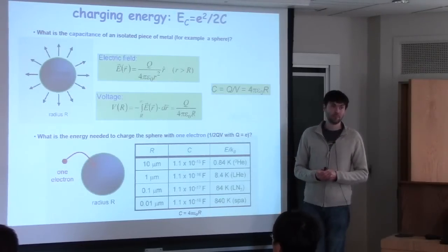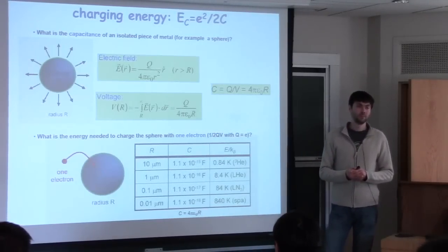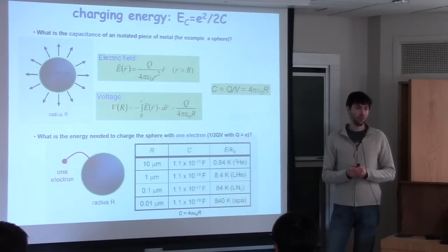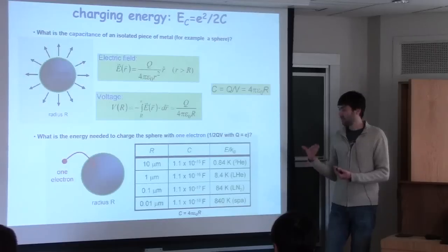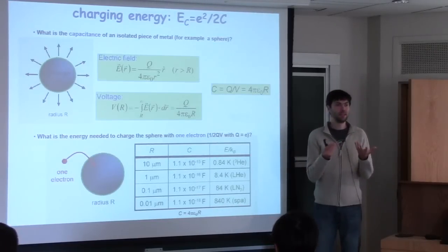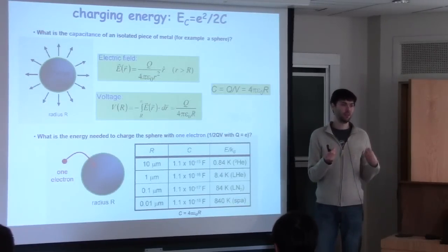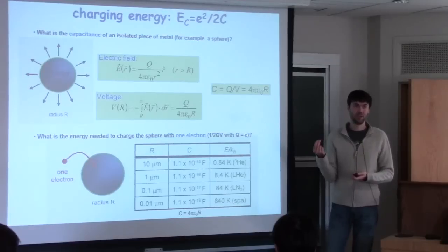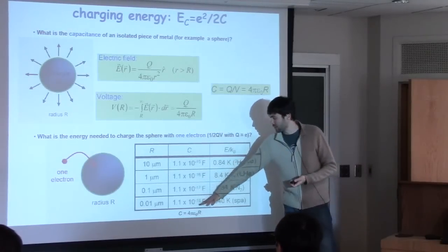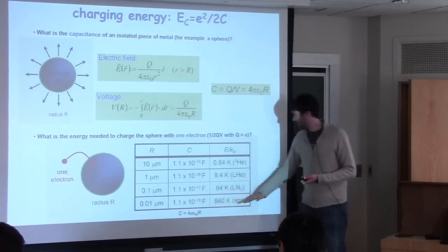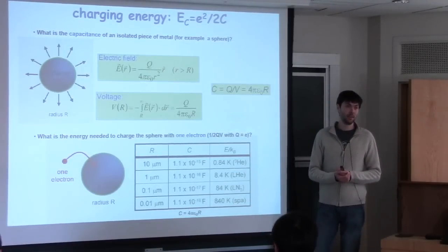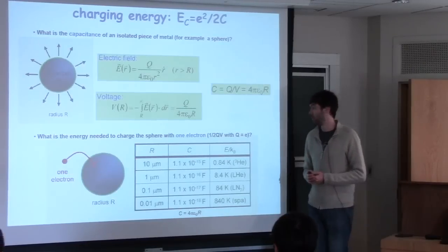So this is telling you at what temperature you would get spontaneous charging, not when you're actually applying external voltages? Yes, that's one way to look at it. Or, like I just said, at what temperature you would not see a difference between an electron being there or not. At what temperature are the single electron charging effects relevant? If we talk about nanostructures, down here, then pretty much below 100 degrees Kelvin, charging effects from single electrons become relevant.